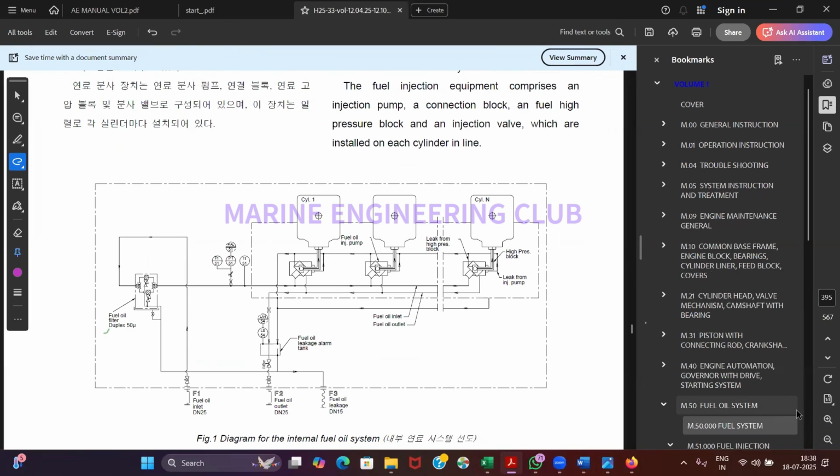यस सर। मेन इंजन में तो सर पंचर वॉल्व होता है, इसमें क्या अरेंजमेंट होता है सर? मेन इंजन में पंचर वॉल्व ऑफ सिंगल यूनिट तो आप कट ऑफ करोगे. मेन इंजन में फ्यूल कट ऑफ इज अ डिफरेंट अरेंजमेंट. To cut off the fuel, you lift the roller. In the main engine, the roller itself is lifted up from the cam. So if the cam is not touching the roller, then it will not lift, not do any compression in my fuel pump. Agreed? Okay, पंचर वॉल्व मत बोल देना गलती से वहां पे. पंचर वॉल्व ऑपरेशन इज फॉर all the pumps together. That will come tomorrow.